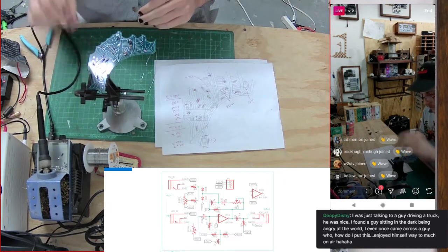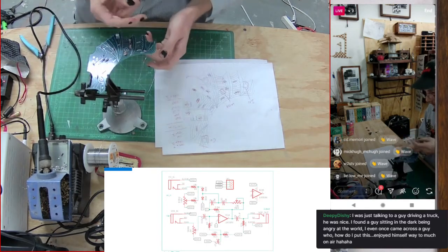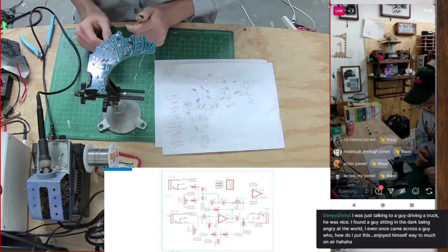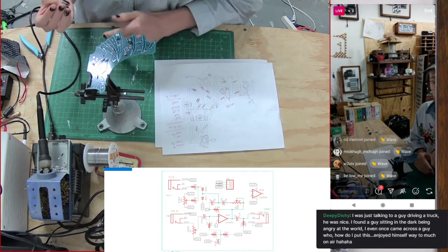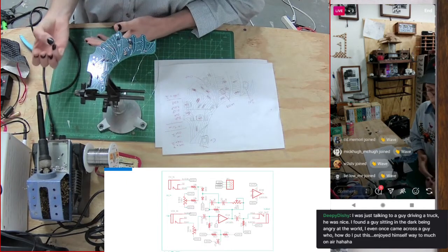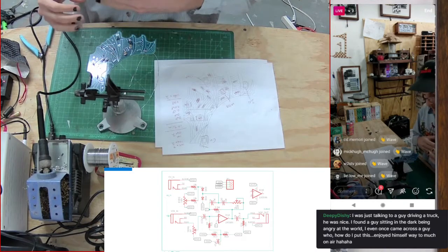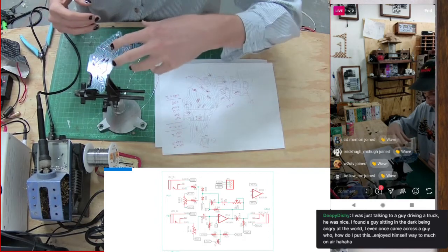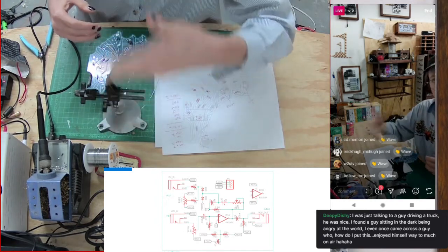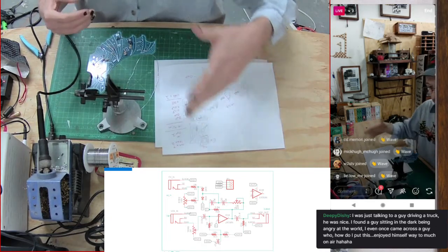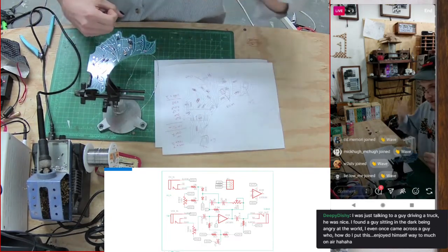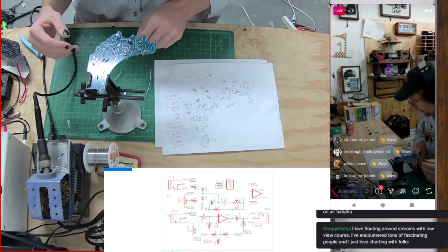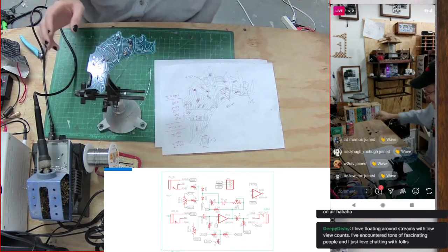And so you'll have one port to plug your source into, and then another port to send it out to whatever your mixer or sound source is. And then there's going to be a third one, which is for CV, or control voltage. That'll be so that we can take another signal or sound source and send it in here to modulate how much the frequency is open, or how much the filter is open. If you have it really subdivided, you get a crazy sound when it's running through. But I'm getting ahead of myself.